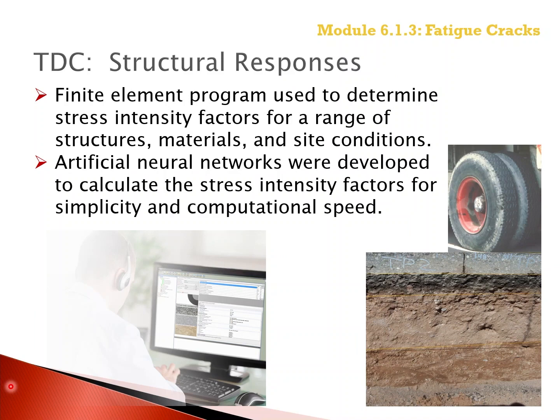Similar to the rigid pavement model discussed in Module 5 for calculating the structural responses, a finite element program was used to calculate the stress intensity factors for a wide range of structures, materials, and site condition factors. For example, different traffic loads, different axle geometry configurations, different material properties, different layer thicknesses, different support conditions for flexible pavements.